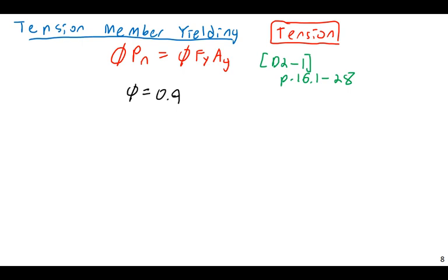So you may design it thinking, okay, according to my calculations, this member, if built properly, will be able to resist a tension load of 2,000 pounds. But there is always some variability. Maybe the steel that you get from the mill turns out to have some small defects in it. Maybe when they install it, they don't put exactly the right amount of tension on the bolts. Or maybe when they install it, they cut it a little bit too short, and it ends up having a slightly different cross-sectional area than it should. So that is what your resistance factor is meant to account for.